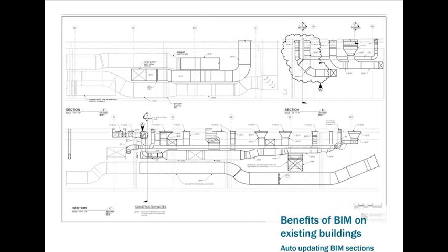We're also able to speed up production by creating sections to show the stuff that was going on in complicated areas, and because it's all looking at the same model, these sections would update automatically. So we didn't have to go chase our sections. And as we're issuing a series of submittals, it can take a lot of time to keep this stuff all up to date. So this was a huge help.